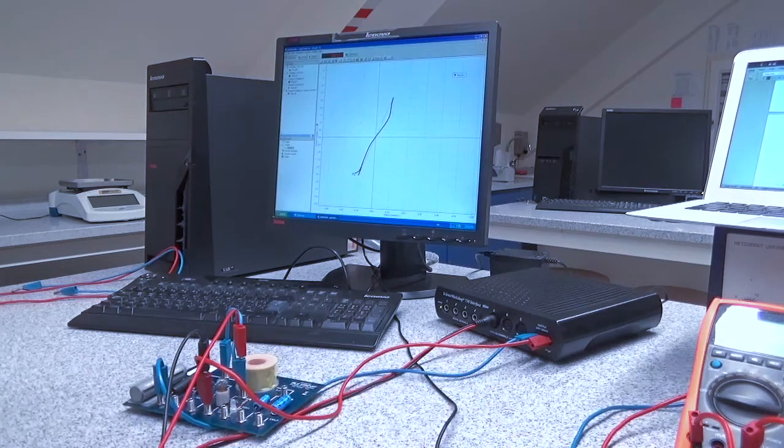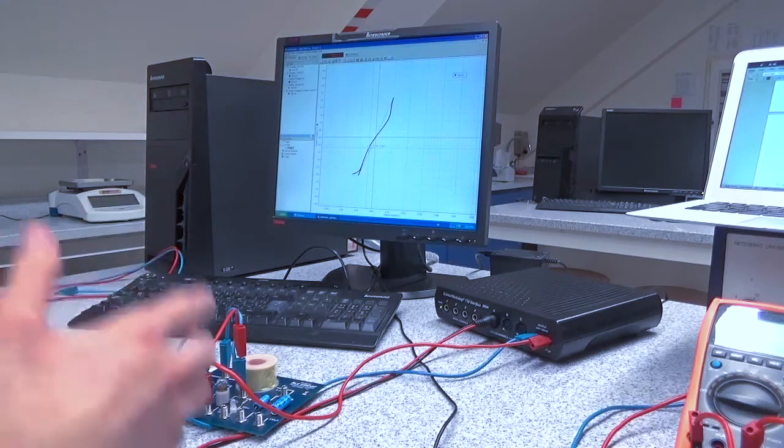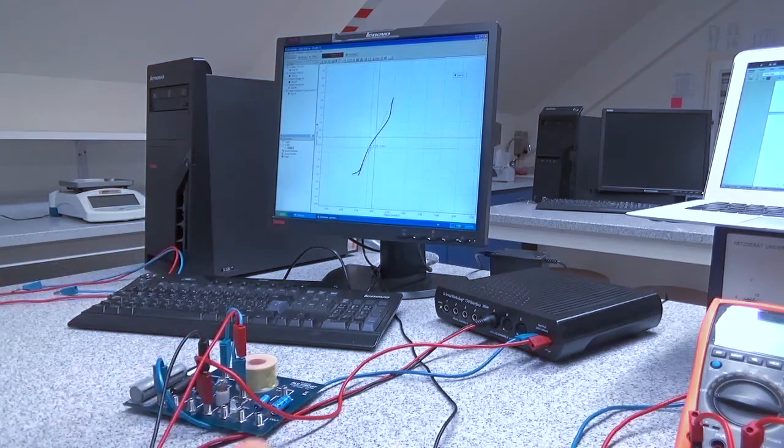And in a similar manner to what we have done before, over here you are going to click on that XY coordinate delta tool, and you are going to pick 4 arbitrary points for the voltage and the current. For each value of X and Y, you are going to be determining R, which is the resistance. We know by Ohm's law that V equals IR, so R would be equal to V over I. By determining each value of the resistance, you would be validating that for a light bulb, the resistance is not a constant, but rather it varies from one point to another, which is an indication that the light bulb over here is a non-ohmic device.